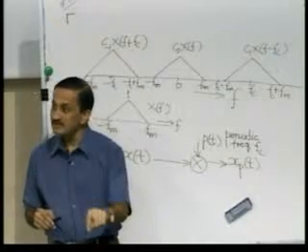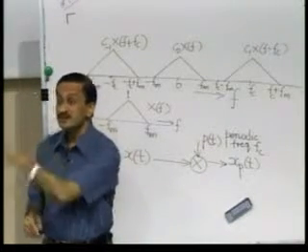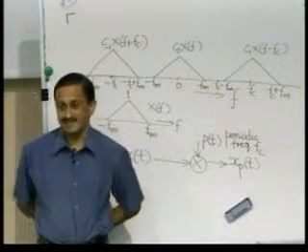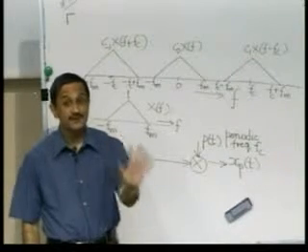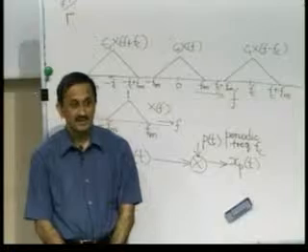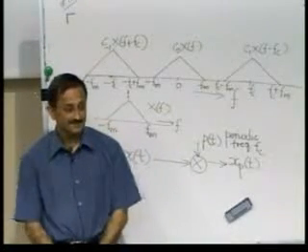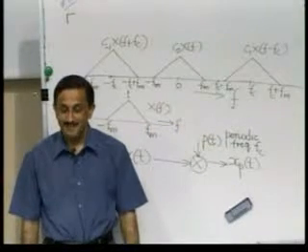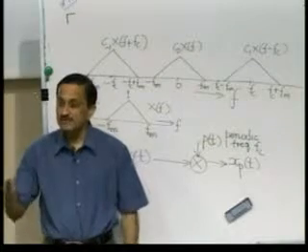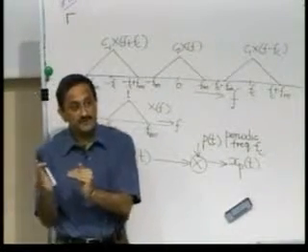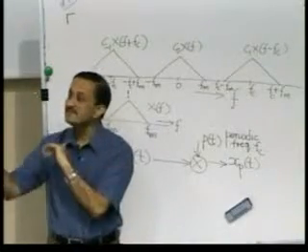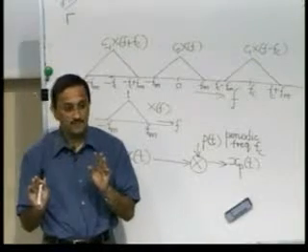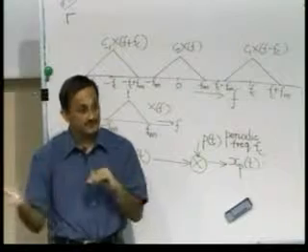So, instead of putting a low pass filter, we could now put a band pass filter around the multiple of the carrier that we want. So, suppose we want the carrier frequency to be 3 times Fc. Suppose I want a carrier frequency of 3 megahertz, but I have a gating pattern only of frequency 1 megahertz. Then in this process I have already created a replica of the spectrum at 3 times Fc. So, I could put a band pass filter with a pass band from 3 Fc minus Fm to 3 Fc plus Fm.